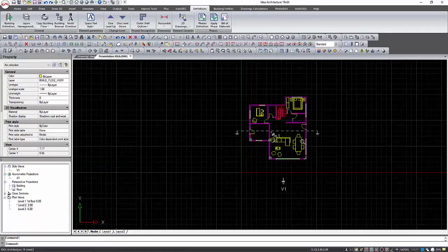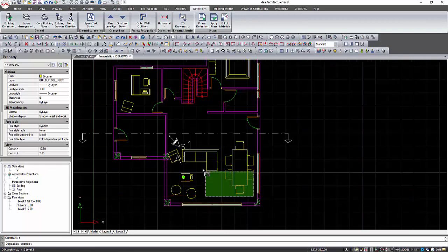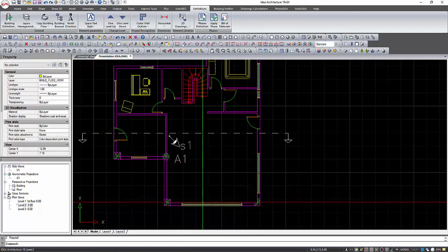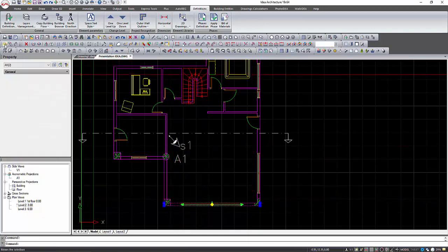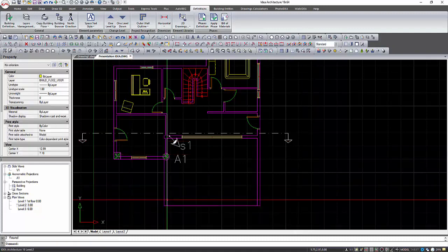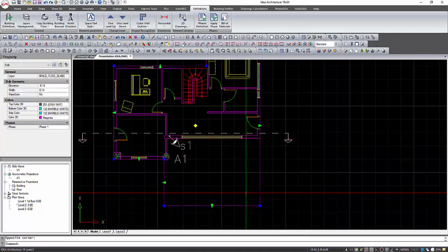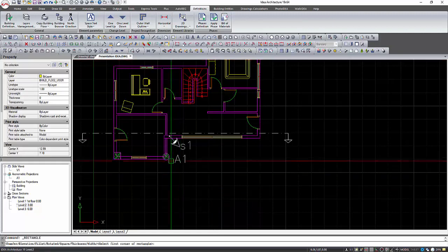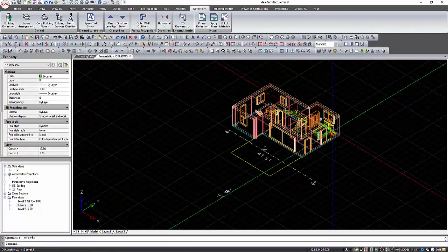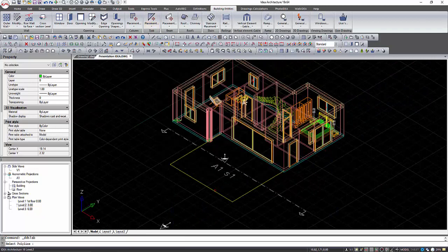Back to the plan view, let's continue by making some changes in the second floor. Let's delete these entities. The walls should be moved a little. And let's create also a new balcony in this second floor. First we design the slab from a simple rectangle. We can turn any shape into a slab as we have already seen.